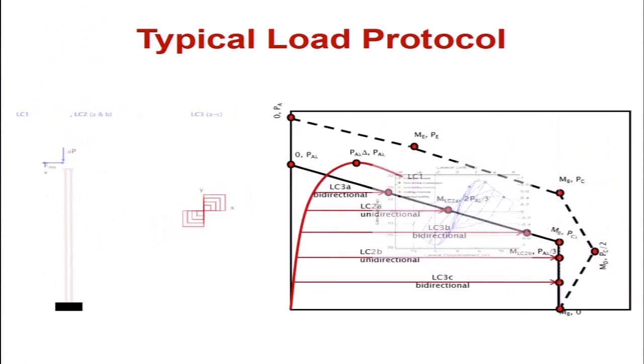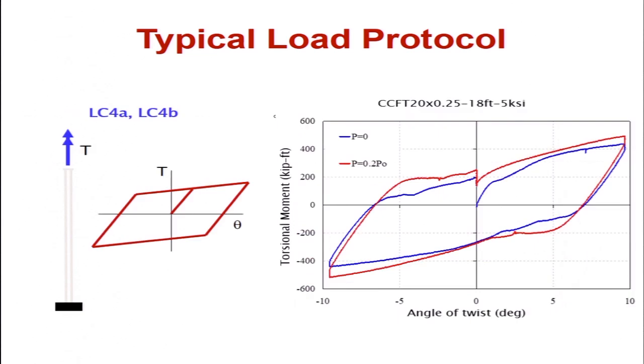And again, the last thing we did was to actually do torsion on these specimens, and these are actually the only, as far as I know, the only well-documented torsional tests on any kind of concrete filled tube section. And we did this for all of our specimens whenever possible.